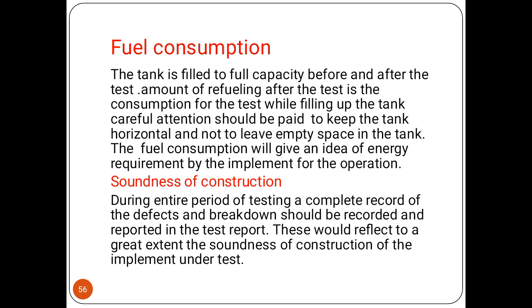Now, fuel consumption is a very simple method of measurement. The tank is filled to full capacity before and after the test, and the amount of refilling after the test is the consumption for the test. While filling up the tank, careful attention should be paid to keep the tank horizontal and not to leave any empty space in the tank. Therefore, the fuel consumption will give an idea of the energy requirement of the implement for the operation.